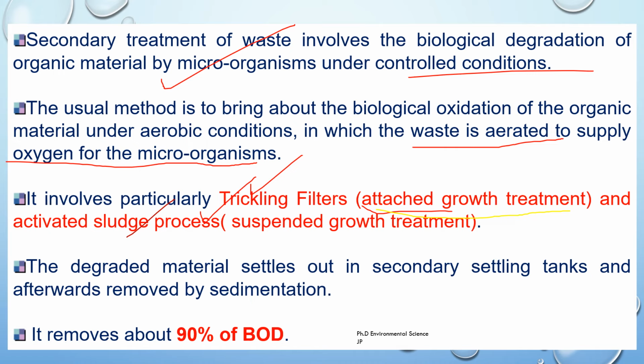After aeration, the wastewater and activated sludge mixture moves to the settling tanks where the sludge settles out and a portion of it is recycled back to the aeration tanks to maintain microbial activity. After the biological oxidation process, the treated wastewater and the biomass or sludge from the activated sludge process or trickling filters are directed to secondary settling tanks.